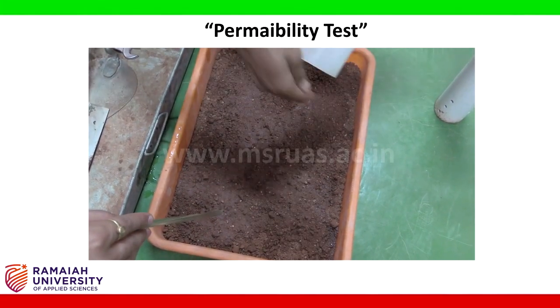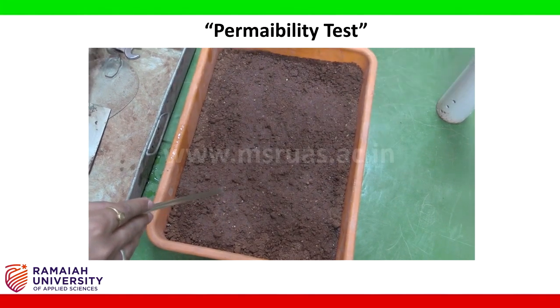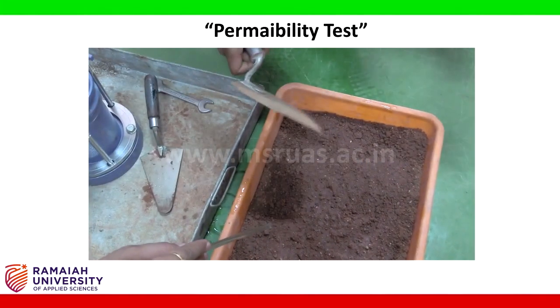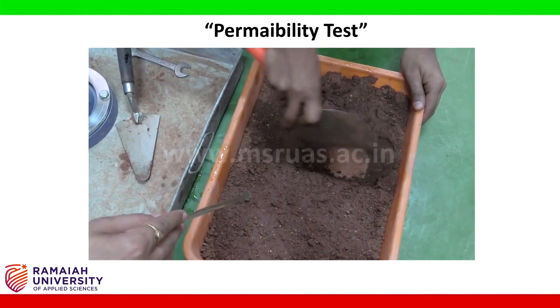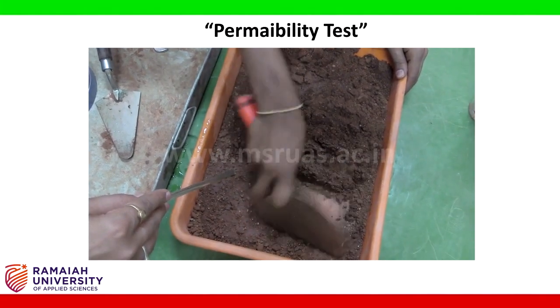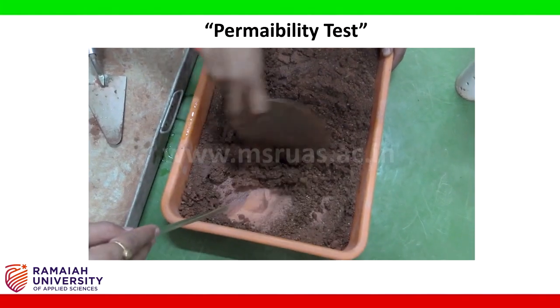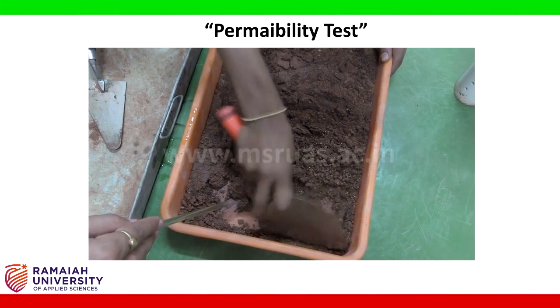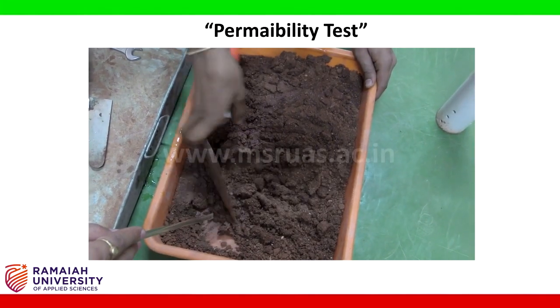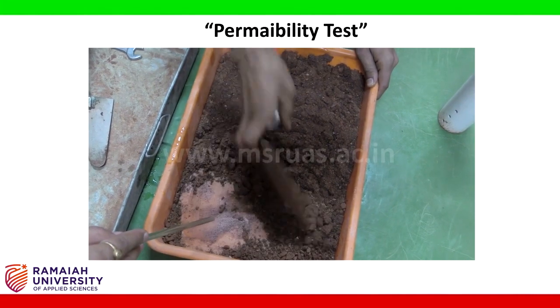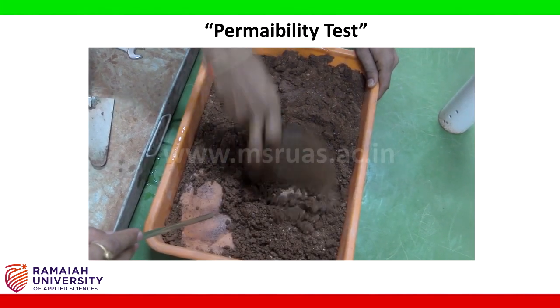Mix the soil now by making use of the trowel evenly such that there are no lumps left in the mix. This being a coarse grained soil, a granular soil, we are going to make use of this material to conduct the constant head permeability test.